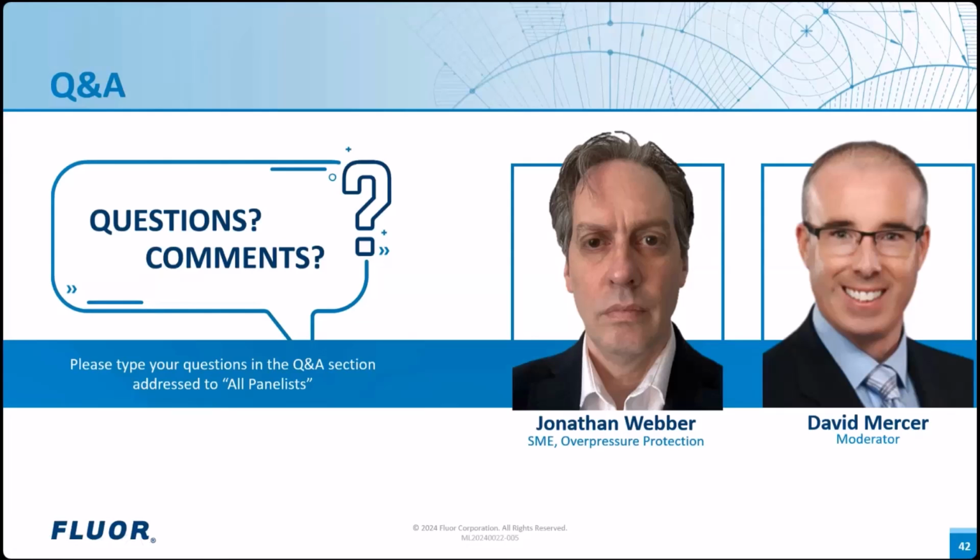But I think maybe the question might be expanding a bit beyond the specific use of the word HIPPS that I've used in this context. I've used the word HIPPS specifically to refer to instrumented systems that are used to replace the PSV or reduce the required relief load, in that regulatory sense.